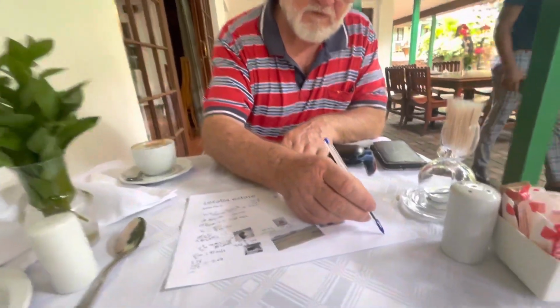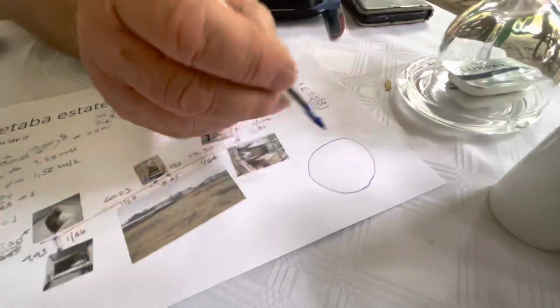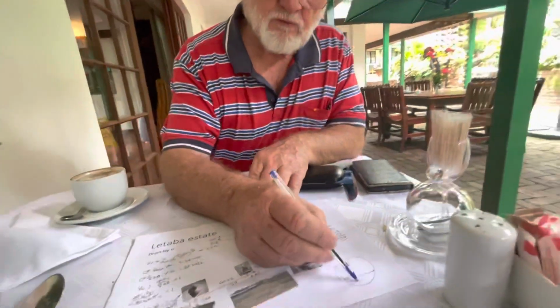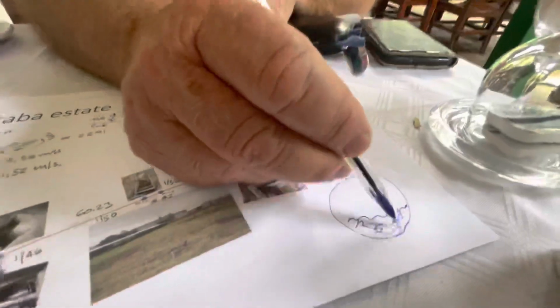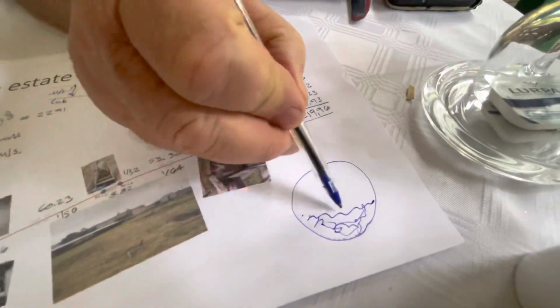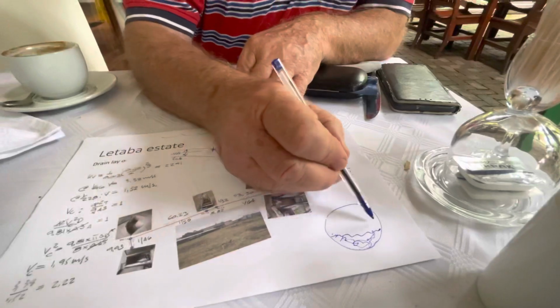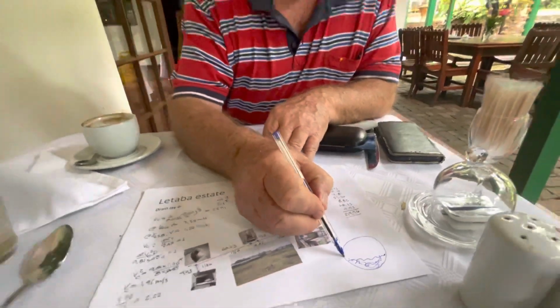So what happens is, instead of having a circular cross-section of flow, what you've got is all your stones down here, and then this is rougher. Right. So your capacity is reduced phenomenally. Yes. So if your pipe is half full of silt, then you'll only get a quarter of the amount of water through there, not half the amount.